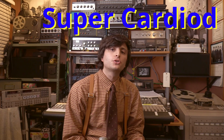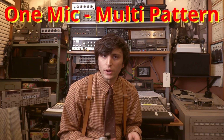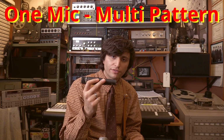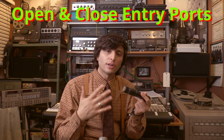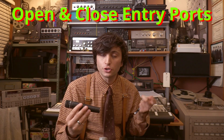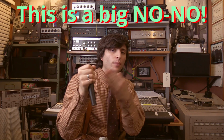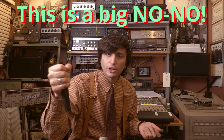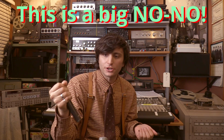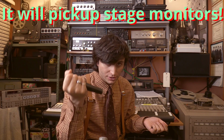And there are ways to have multiple pickup patterns in one microphone. The first and easiest way is to have a cardioid microphone and have a physical way to block off the rear and side entry ports, thus turning it into an omnidirectional microphone. A really simple example of this happening is if you see a singer on a live stage wrap their hands around a cardioid microphone when they're singing, and now that microphone has turned into an omnidirectional microphone, and they might start to have feedback issues because now this microphone is not going to be rejecting sound coming from off-axis locations.